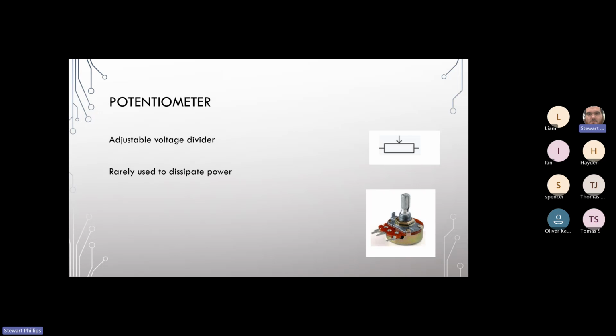Variable resistors can be used to adjust circuit elements such as volume control or a light dimmer, an old school light dimmer. They operate by a mechanism, and can be used as a position transducer for a joystick or throttle position sensor. The thin carbon film that makes up the mechanism cannot dissipate any meaningful amount of power, so a potentiometer is usually used to control the output stage of a circuit.